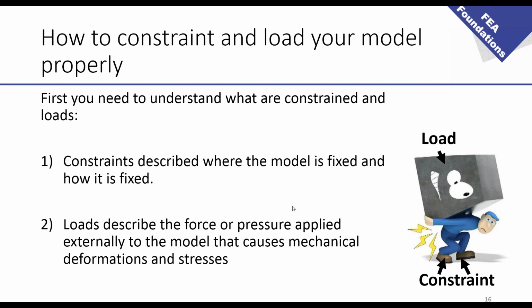Now let's talk about how to constrain and load your model properly. This is very basic, because a lot of people asked us, what is a constraint? At the beginning we were thinking, that's so obvious. But as some people don't understand fully, I decided to present it in a very easy way. Constraints describe when the model is fixed and how it is fixed. And loads describe the force or the pressure which is applied externally to the model that causes the mechanical deformation and stresses.